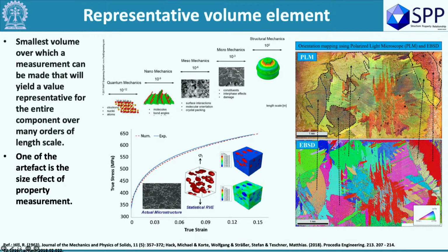People who work with fatigue, I think Somjit works with fatigue, know the difficulty. You just change your sample, same batch, same thing, and the fatigue life will be different, because one will contain a single pore and another one will not. That severe it is. The data generated from here possibly goes into making the bridge. Out of hundreds of fatigue tests, you generate one single curve, and that curve is used for the life of the bridge. It's as simple as that.